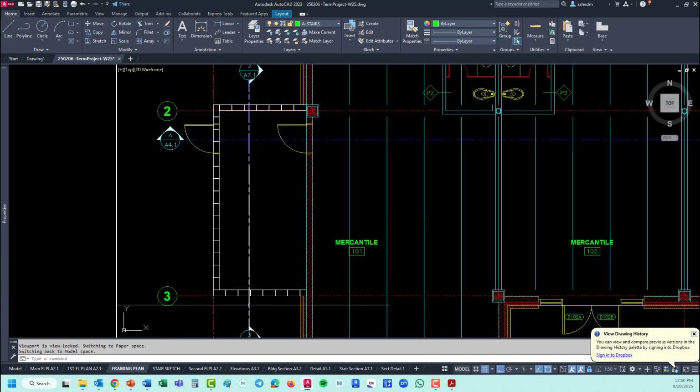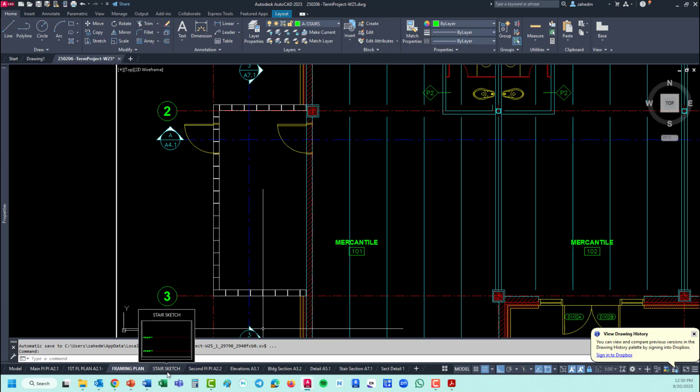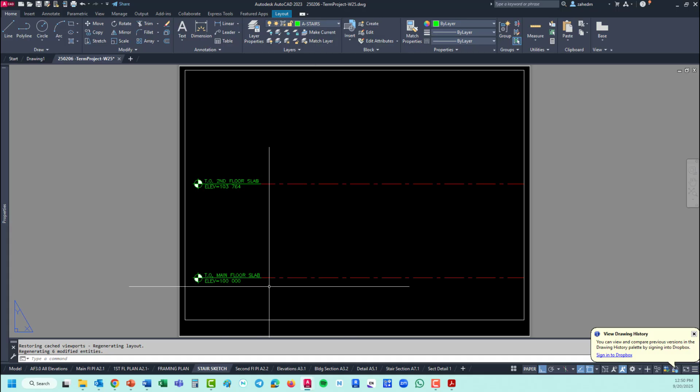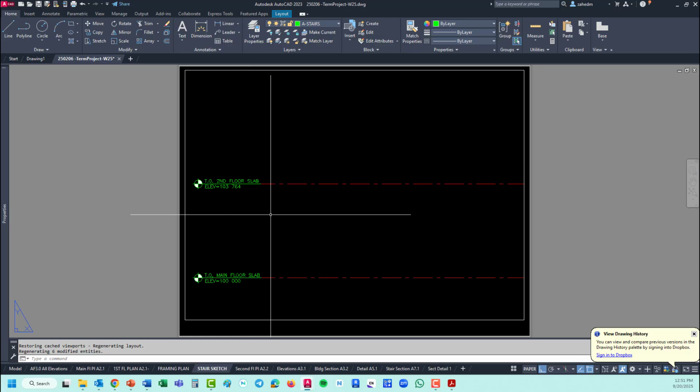Okay, so here we are. We want to cut through these and then create a staircase right in here. And then how we are going to do that. At the bottom of this page, as you can see, this is a sketch. I laid it out already. We start from the main floor slab, or better yet, first floor slab, and then bumping it up to 3,764. So this case provides the floor to floor. The wall height was 3,600, 164 added to 3,600, which becomes 3,764 for the floor to floor height.